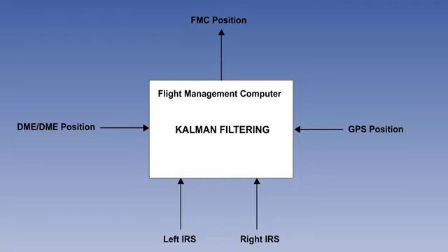The later generation of inertial systems, which are generally known as Inertial Reference Systems, or IRS, are usually part of an Integrated Flight Management System, FMS. In the Flight Management Computer, or FMC, there are usually 2 or 3 IRSs, each generating its own present position. These IRS positions are compared with independent sources, such as Global Positioning System or GPS, and computer-generated calculation of crosscut positions, which have been obtained from ground-based radio beacons, called distance measuring equipment.